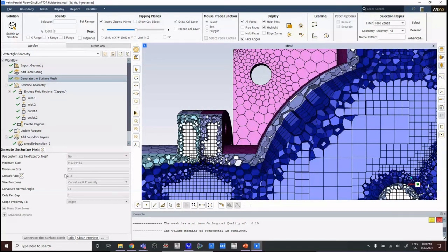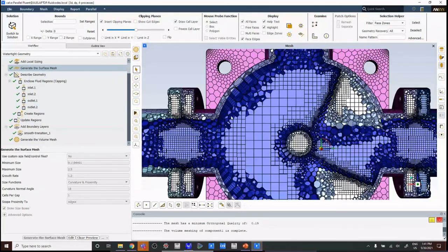Okay. All right. A quick question. Asad Ali says, can we use Fluent Meshing and export the same mesh in Mechanical or structural? No, that's not possible. No, it's not compatible. Polyhedral is just specific for fluid dynamics. For Fluent, just to be precise. It's not compatible with CFX, actually. Just Fluent.